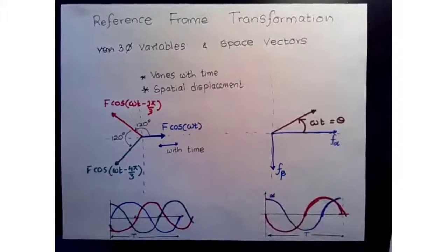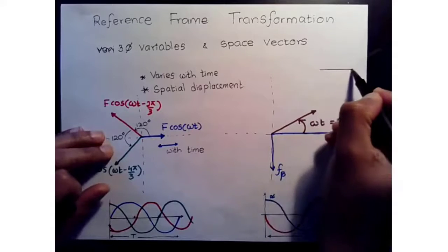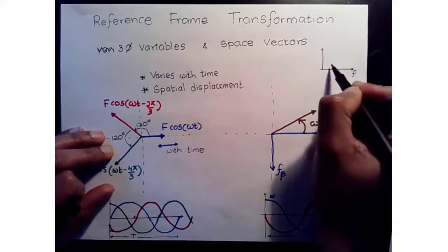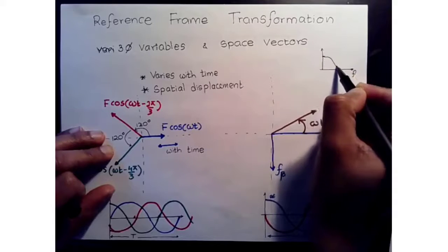This is a little bit different. I know what you are saying. You are saying, okay, if you are looking at it from a frequency response perspective or a Bode plot, that is only specifying how the gain works across different frequencies. So in a Bode plot, that basically says, at this frequency you have this much gain or this much amplitude. So for a low pass, it's going to look something like that.